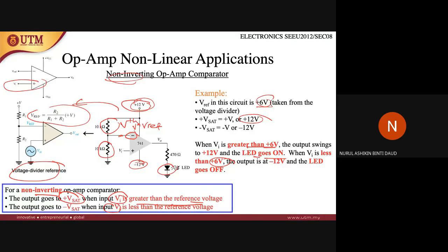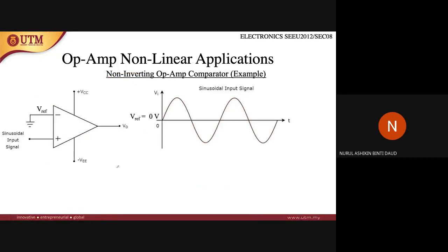If it is non-inverting and VI is greater than V reference, it will be positive saturation. So this is for non-inverting.